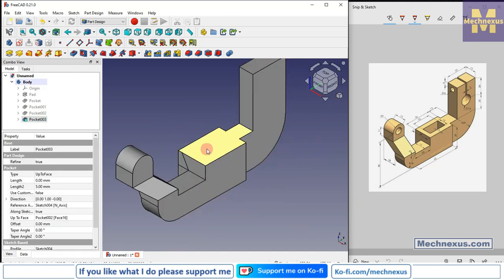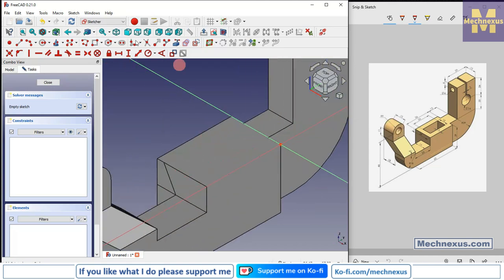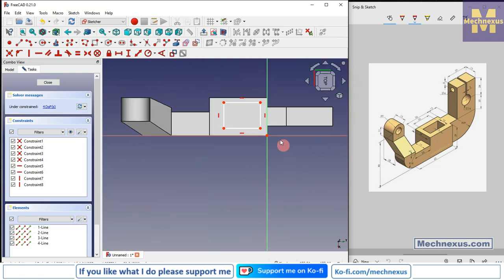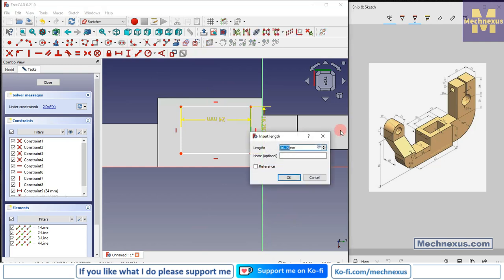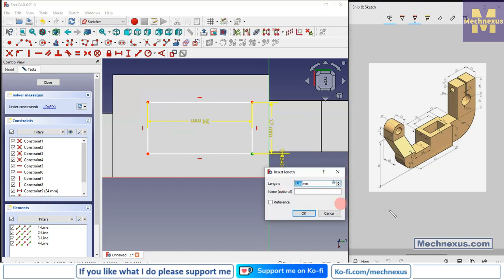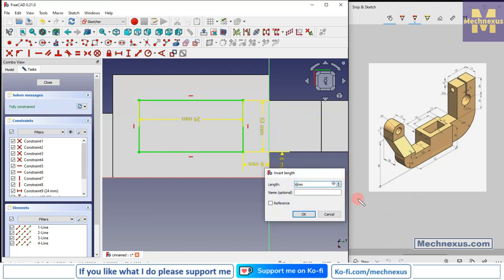Now we will select this top face and click on the sketch, switch to the isometric, and at the top we will create a rectangle, and now we will rotate our model, select this dimension and provide the dimension of 24, and select a vertical and give it a 12, select this and this and this 6 mm, and select a horizontal dimension, and this is 6 mm.